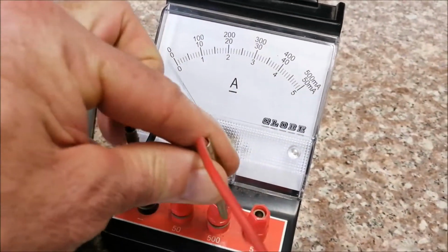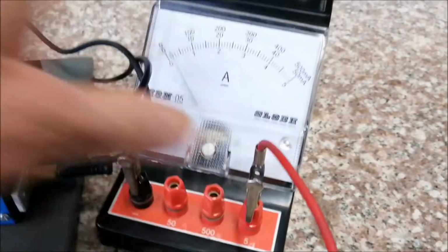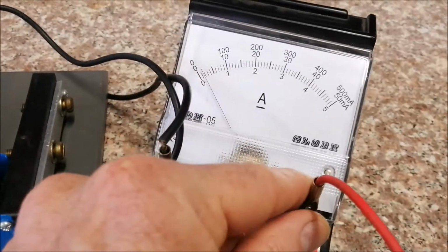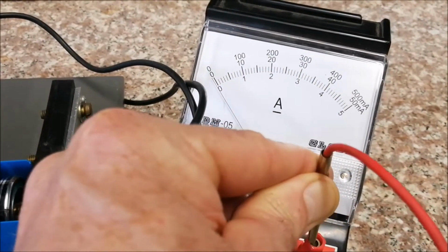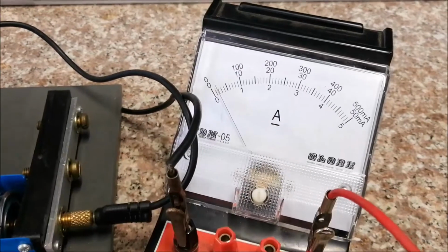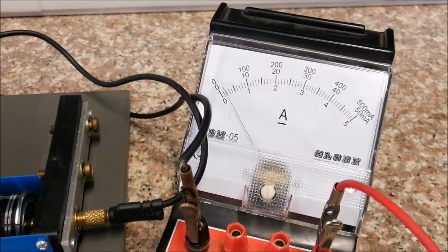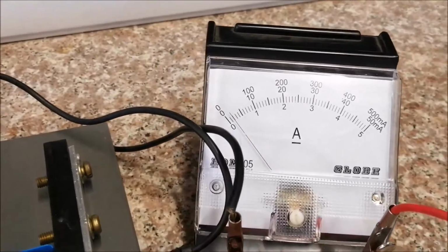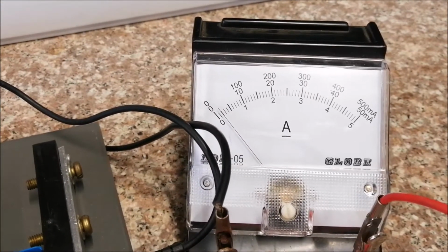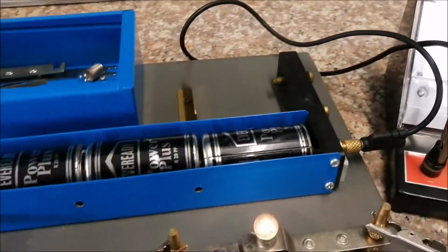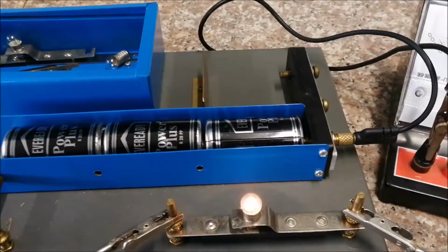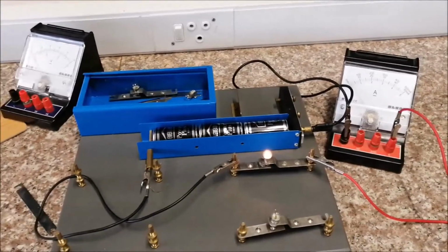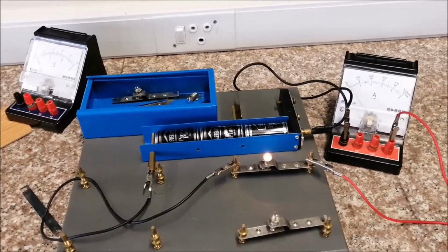Now, if we wanted to actually read the value of current, we just need to change the scale of the ammeter. Now you can see that it is reading, so let's just disconnect and reconnect here. As I disconnect, the needle drops, and as I reconnect, the needle goes up, and you can see that we are getting 0.2 of an amp. If I hold it parallel there, we are getting 0.2 of an amp flowing with one globe, and this is obviously a series circuit because there's only a single path for the current to flow. So that is a series circuit.